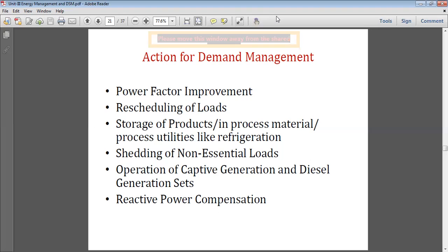Now it is observed that in the morning from 9:30 to 12, and 12 to 4 p.m., the maximum demand occurs. So during daytime, which is our less priority feeder? The less priority feeder is one of the hostels, because all the students come to the college.